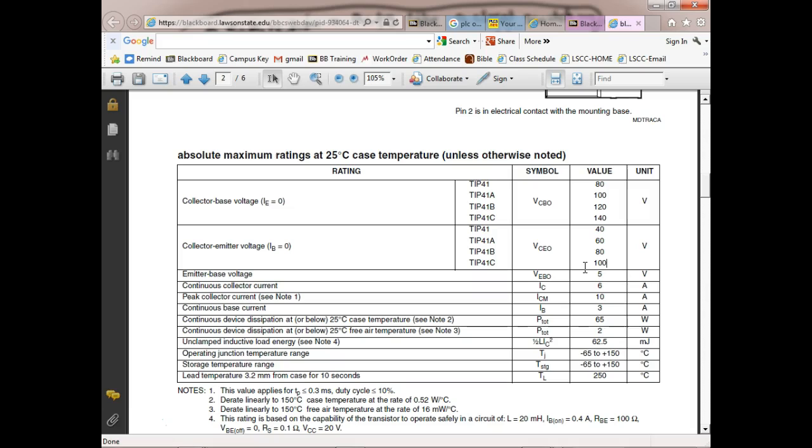So the Zener, we protect it with that RS, right? You understand? But a Zener is designed to work in breakover, but these junctions are not designed to work in there. So it's just like a regular p-n junction that's not a Zener. If you break that over, then odds are the transistor or that junction is going to be damaged. So that base to emitter breakover voltage is very small, so we can't put a lot of DC voltage on our base.